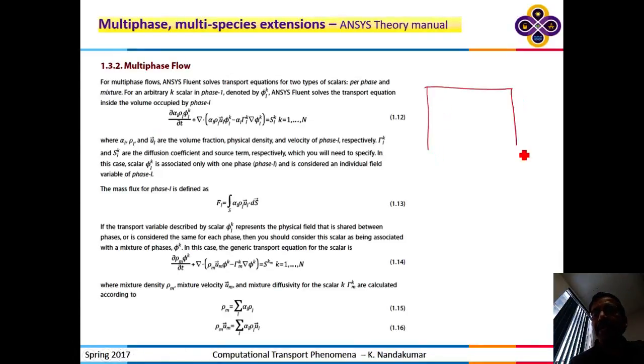Do you remember, did I talk about this in this course? Mixing, dispersive mixing and distributed mixing concept. That's what these two terms manage. So when you want distributed mixing, that is, if you have a cluster of particles and you want to move them around to different locations, that's done by the large-scale velocity field. What kind of circulation you set up.